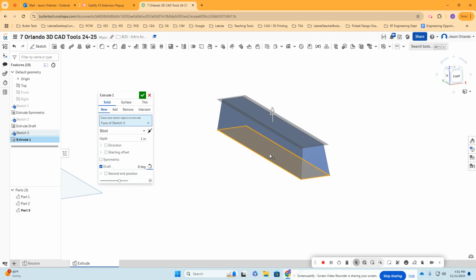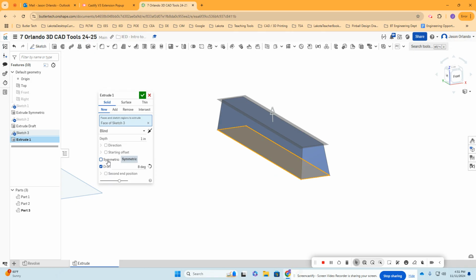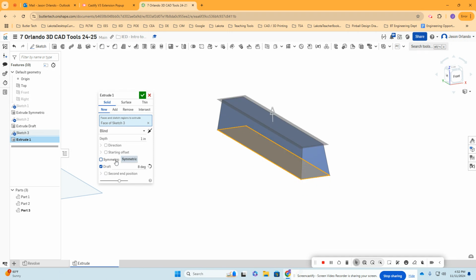So now that's not the end. So what's different? Because we just did that, right? What's different in this one? Do you remember when I used the symmetric button where I could kind of go both directions? Yeah, remember that? Okay. Well, I'm not going to use that this time, but it plants the idea that I can extrude in both directions at the same time. The problem with symmetric is it has to be equal, and I don't want to do it equally this time. I want to go the other way with a different set of parameters, and Onshape allows that right here.